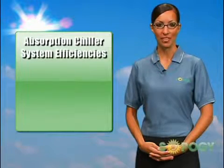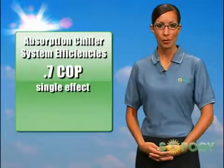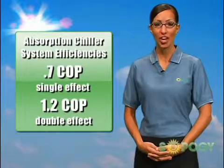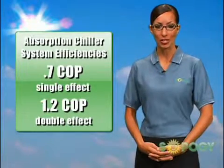Absorption chiller system efficiencies are often around 0.7 COP, or coefficient of performance, for a single effect, or 1.2 for a double effect absorption chiller, making for a good complement to the efficient Sopogy micro CSP solar collector. Soponova is the ideal technology for solar air conditioning because of its unique sun tracker, which gives the system higher production and storage, allowing for consistent and reliable operation.